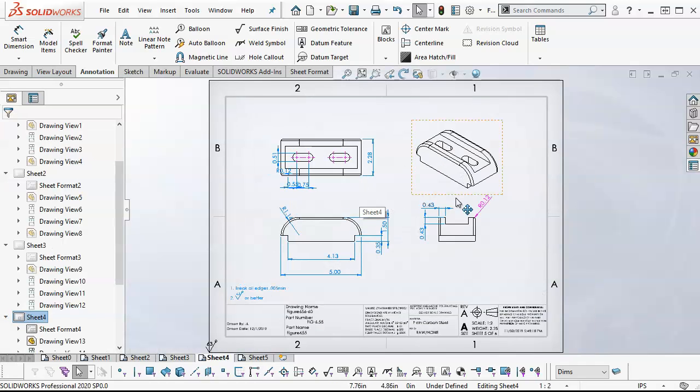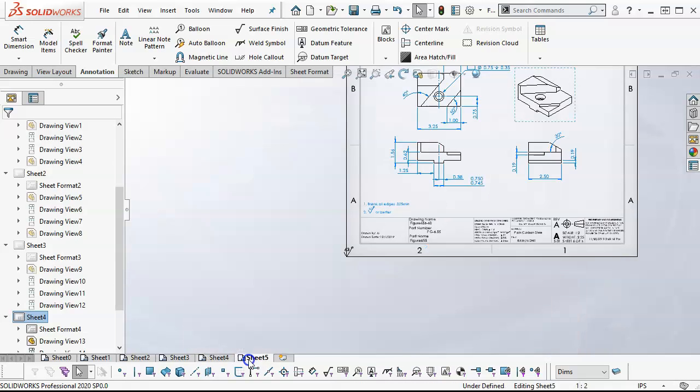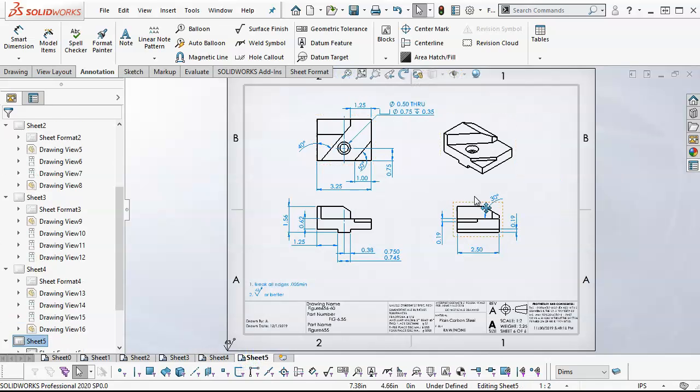Okay, so that gives us pretty well complete. There's still more cleanup, but as I go through these passes, typically I'm looking at this in terms of a subassembly. So part of my iterative process is to bring in the first part, basically building a roadmap of how the subassembly is going to be constructed. I'm starting to think about how the pieces fit together, where the tolerances are going to stack up, and dialing in those numbers as I go. So I don't have to think about it all at once, but it becomes a progression and an evolution of the project.